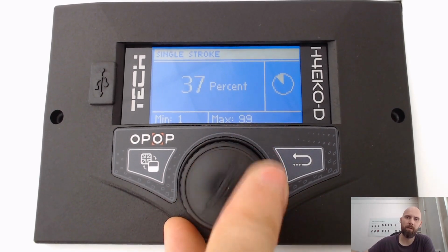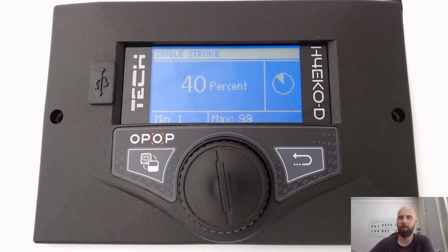So when the water inside the floor heating is heated up to dedicated temperature, the mixing valve should close itself as fast as possible. So by increasing this number, you basically make sure that each step will take, for example, here 40% of the full range of motion of the valve.